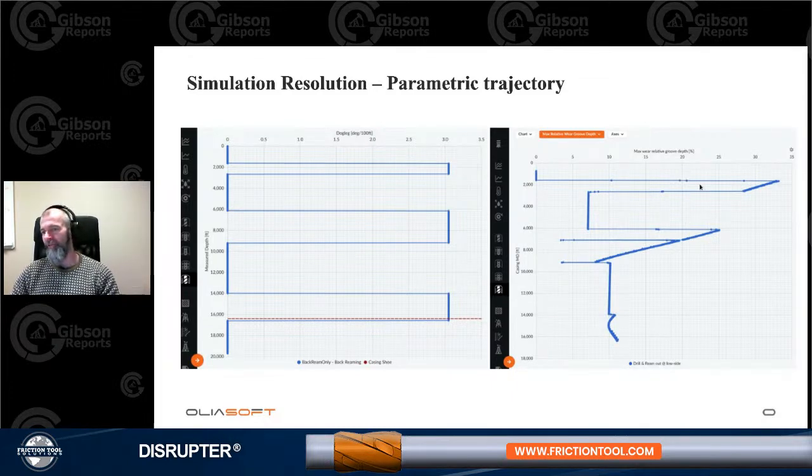I should say I applied not the realistic wear constant here, because obviously it's just two operations, and you can see it's at 30%. So I think I multiplied the wear factor here by about 1,000 to get some values that are not 0.000, etc., just for illustrational purposes. But what you can see here is that the groove depth has accumulated to something like 3.5 times as much at the top, maybe as we expected when we looked at the side force.